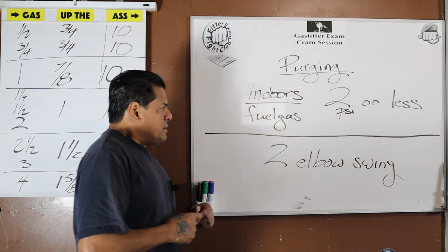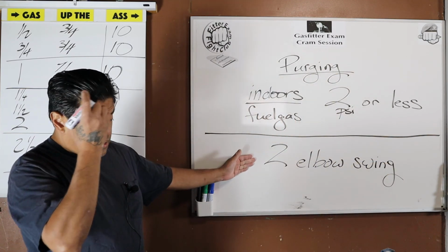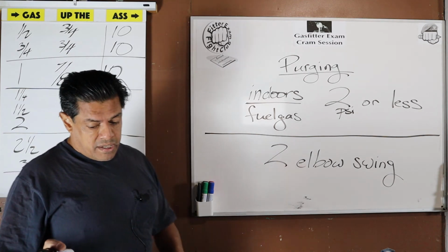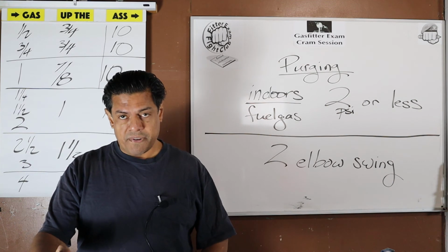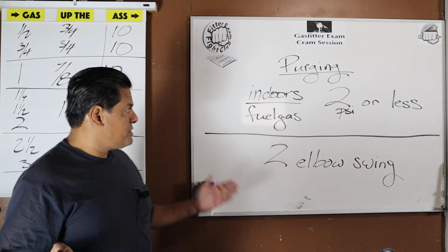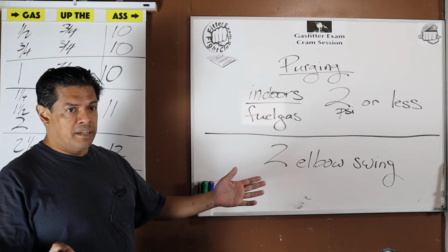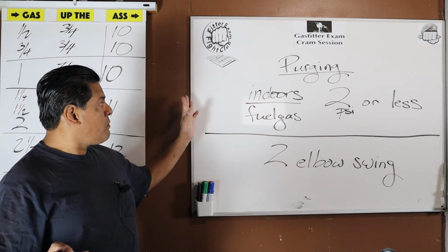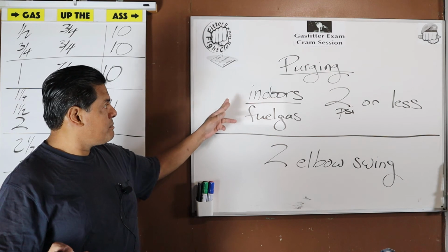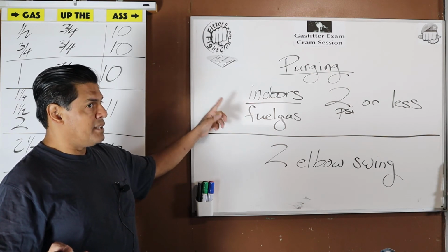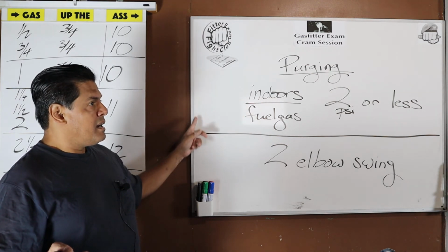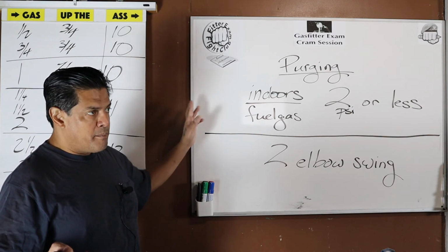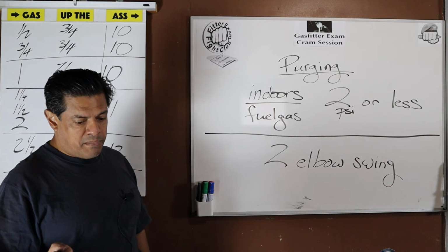Now, we don't need to make a big separate deal out of, okay, that branches shall be taken off a gas riser, and then branches shall be taken off a main, a horizontal main. If you remember when I was drawing the picture for the test T and drip leg downstream of a lockable supply valve, I had my little horizontal main and I already put 2 elbows on there. I automatically 2 elbow swing off that main.